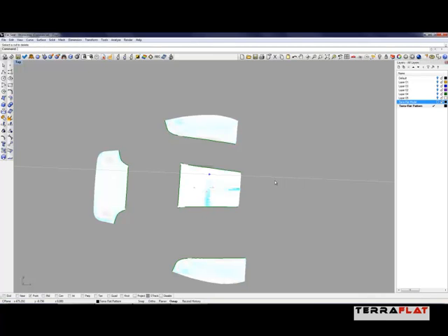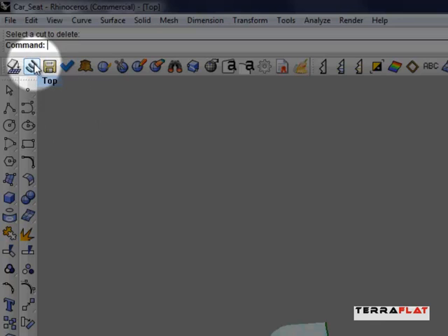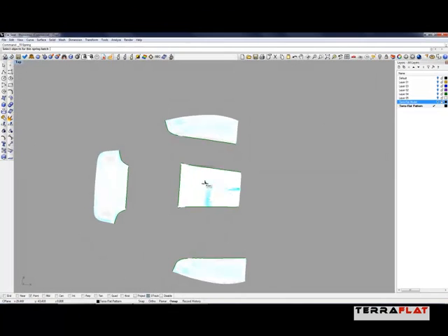So we have those pieces put back together. Once I do that though, I want to go back in and spring this piece, because you can see there's a little bit of stress that's been added to this piece when I've sewn them all together, which would make sense. So I'll click this, hit enter on my keyboard, and I'll simply go through and reflatten that piece. And now we have a piece that's ready to go out for cutting.